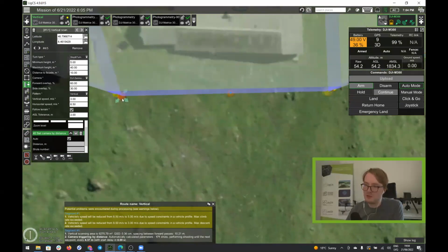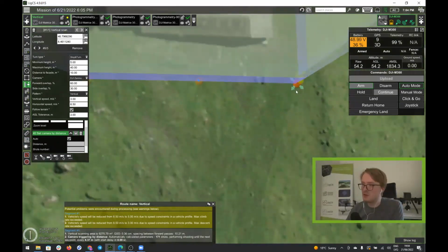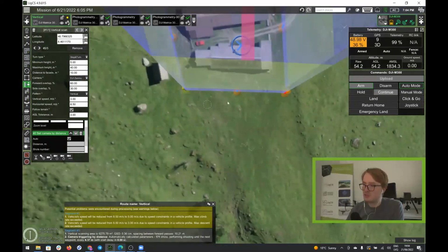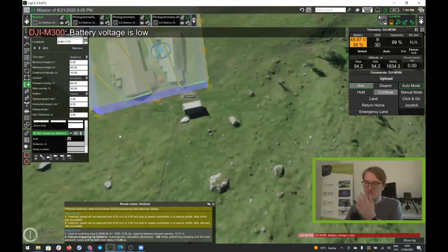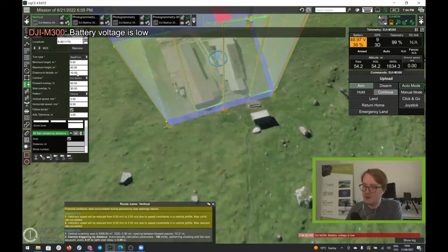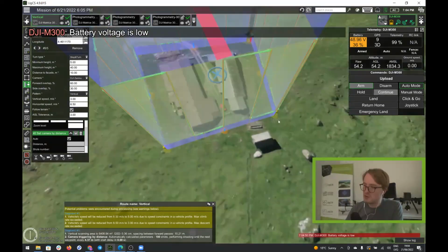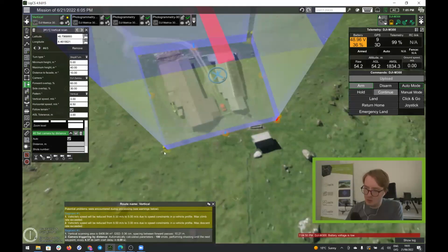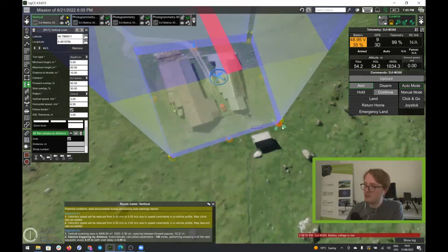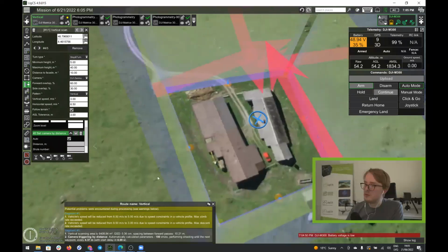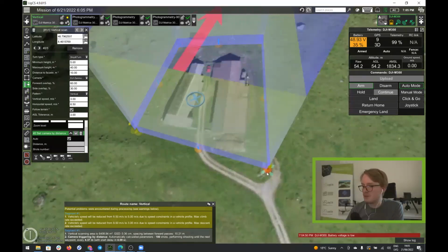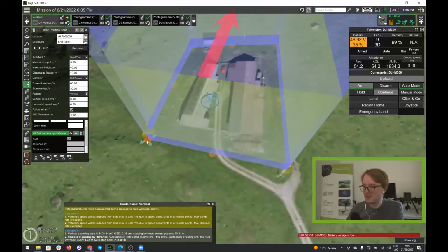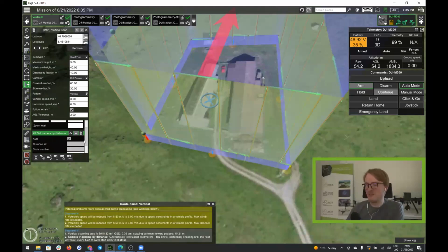So this is basically just the tool that I like to use to make sure that the distance to the object is how it's supposed to be, because the more accurate this will be, the easier it will be when you'll be doing data processing. Also, depending on the distance to the facade parameter that's here, this will impact how close the survey lines will be and what the overlap between the images will be. So I'm just going to eyeball it for now. I think this should be more or less good. Again, it's interesting how we're imagining this farmhouse would be like some tall building, but you know, I'm just working with what we have right now.